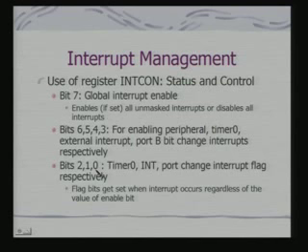For enabling or disabling those interrupts, there is a flag bit that is set when an interrupt occurs regardless of the value of the enable bit. If the enable bit is set, that means the interrupt is enabled, and the interrupt is responded to. Otherwise, the interrupt may not be responded to, but the fact that the interrupt has occurred would be recorded in the flag bit.